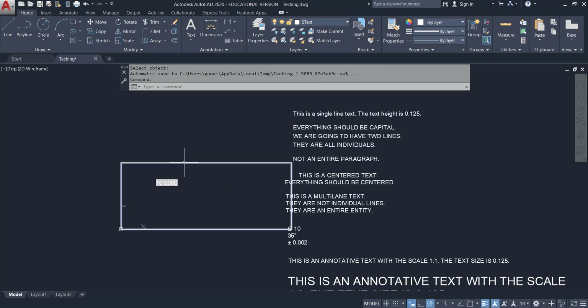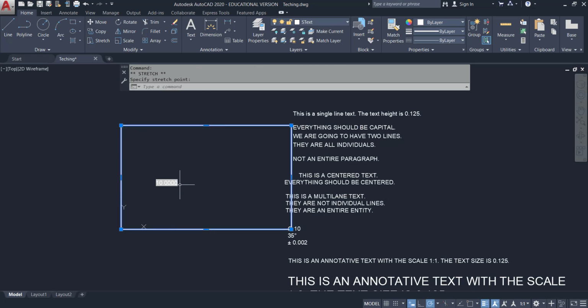Then if we drag the rectangle up, so stretch it up, then you're going to hit RE. So type in RE means regenerate. So the area changed here. So change it back here, then type in RE, then it regenerates and calculates the area for us again.